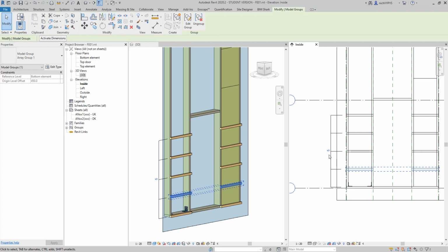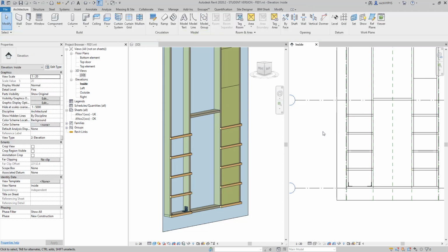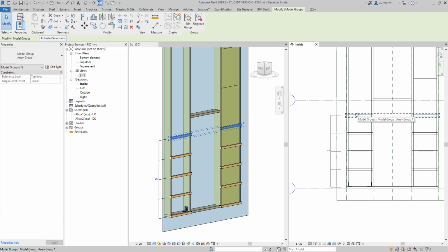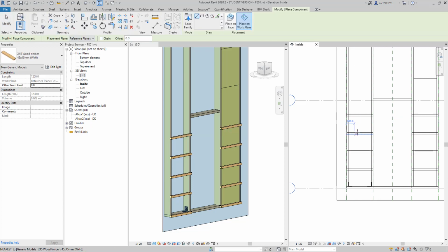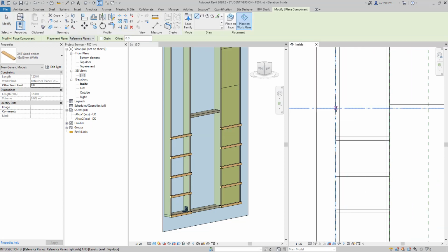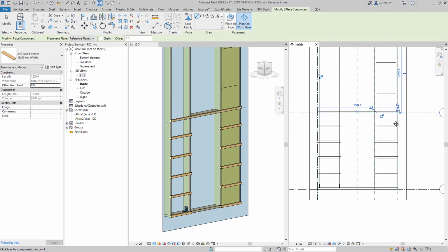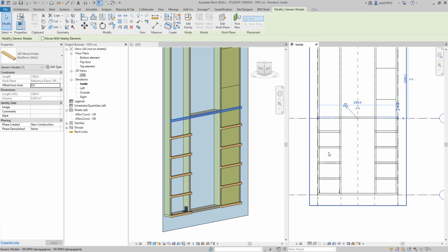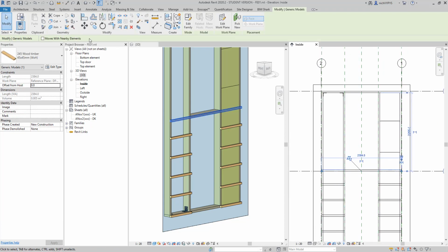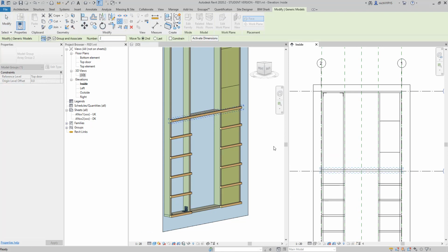And I can adjust how many beams or battens I want to have, 5 or 6. So 5 will be correct here because I want to have a new one going from side to side. So I'll keep those 5 arrays as I have it here, and then create a new 45 by 45 millimeter batten on the top of the door, and continue arraying that to the top.